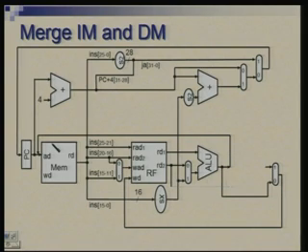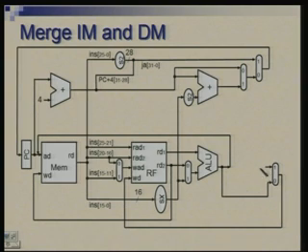Next, the data input which is going here will be now brought to this. So, I have removed the old connection and it gets connected at this point. Similarly, the data which is coming out of memory and was eventually through this multiplexer going to register file will now come from this.